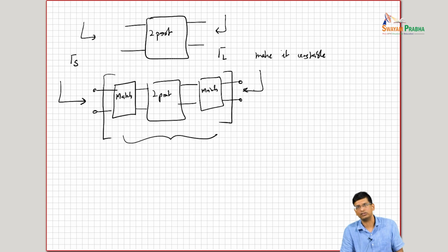just to rely on the matching network, because then you have to be very confident in the loss model of your matching network. So more traditionally, what people will do is add some loss that is intrinsic to the device itself, to make sure that it becomes unconditionally stable, and then design the matching network. Because if everything works exactly like you planned, if the source, the matching network and the load are what you want, then things might be okay.